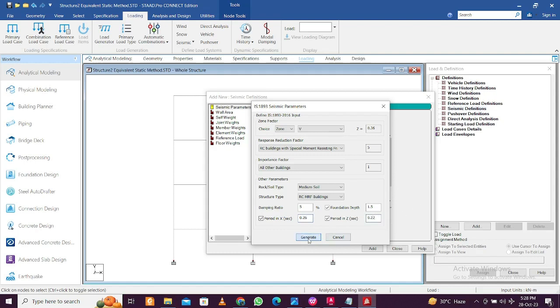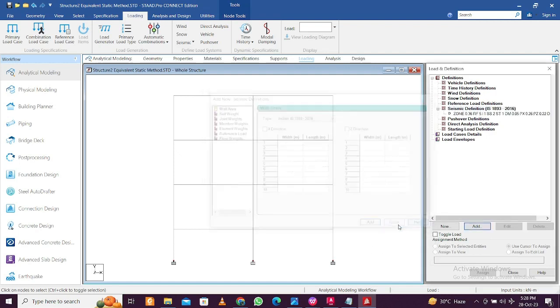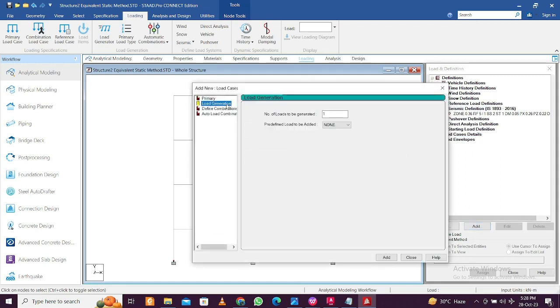And if you use the STAAD editor, you can just directly enter this, no need to create this step as well. You can directly use copy and paste from the text file. I'll also create a shortcut video for this.